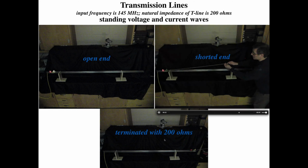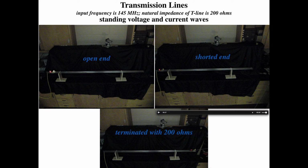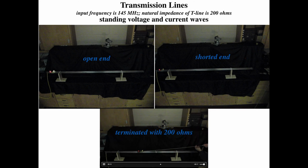And lastly, we're going to terminate the transmission line with 200 ohms. You can't see it, but we've just taken simply a 200 ohm resistor and connected it between the two lines here. Remember, our natural impedance is 200 ohms. In this case, notice that both the voltage indicator and the current indicator bulbs are on. And as we push down, they really don't change at all. There doesn't seem to be any variation in voltage or current as we go down. And in fact, that's characteristic of transmission lines. When you terminate them with their natural impedance, the impedance looks the same everywhere along the transmission line. So clearly, the impedance along the transmission line depends on how it's terminated.